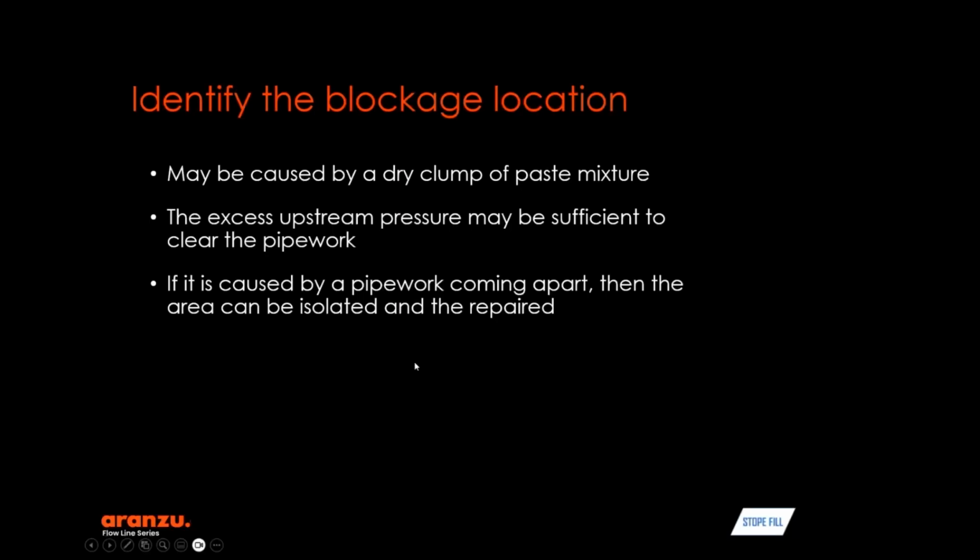At this point, we identify the blockage location, and this may be caused by a dry clump of paste mixture or some loose borehole material if you're using unlined rock boreholes. And the excess upstream pressure of the applied water may be sufficient to clear the pipework. And if it is caused by the pipework coming apart, then the area can be isolated and repaired.